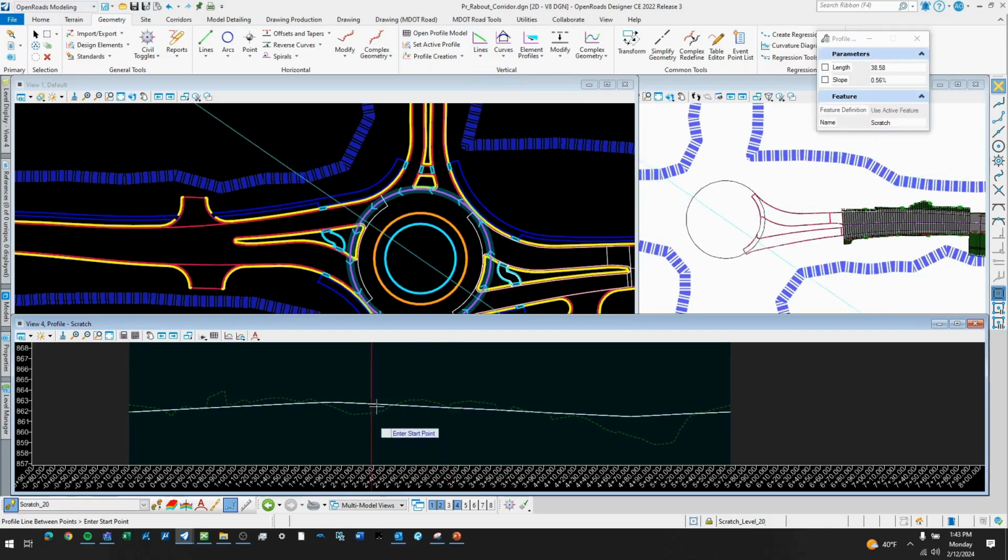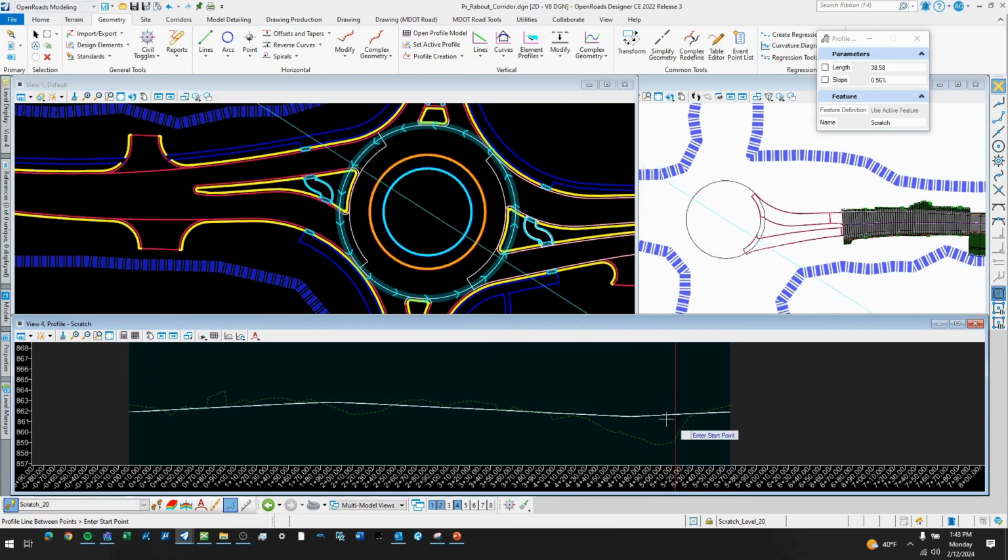This can always change as you go, but I think it's a good starting point. I think it balances pretty well the existing earth that's out there. Obviously, there's a big ditch here that will be filled. That's our low point, right there in that ditch area. Our high point is up in this top corner, and this point here is pretty close to existing ground. So we're hoping the slope stake line doesn't get pushed out too far.